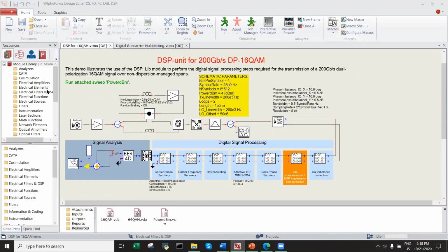So the first demonstration I will show is from the previously mentioned 16 QAM and 64 QAM systems at 200 and 300 gigabits per second respectively, for 200 kilometers of fiber transmission using a 100 kilometer span length. And I will also show the impact of digital backpropagation on the system performance. At the receiver DSP, as we can see here, we have selected the blind phase search algorithm and also the important parameter of the number of pre-symbols, for which 5 are enough for the 16 QAM modulation.